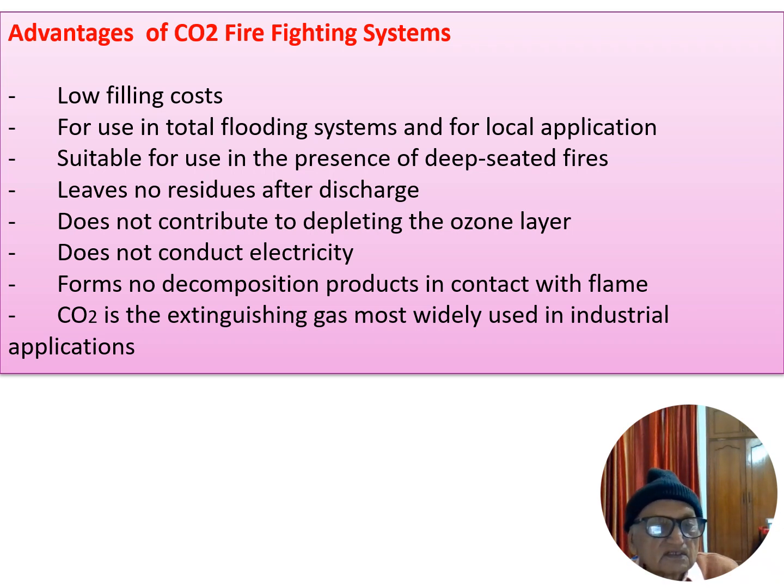Fifth, it does not contribute to depleting the ozone layer. Next, does not conduct electricity. Next, forms no decomposition product in contact with flame. The last, CO2 is the extinguishing gas most widely used in industrial applications.